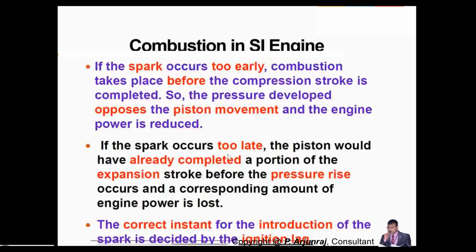If the spark occurs too late, too early is a problem and too late is also a problem. When it is too late, what happens? The piston would have already completed a portion of the expansion stroke. What happens after the compression stroke? The third stroke is the expansion stroke, where the piston moves from TDC to BDC. And again, the same issue will come.